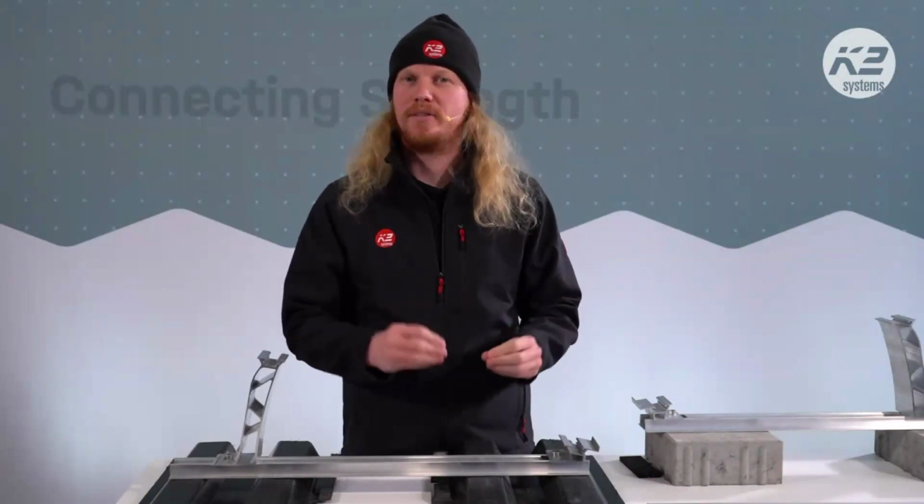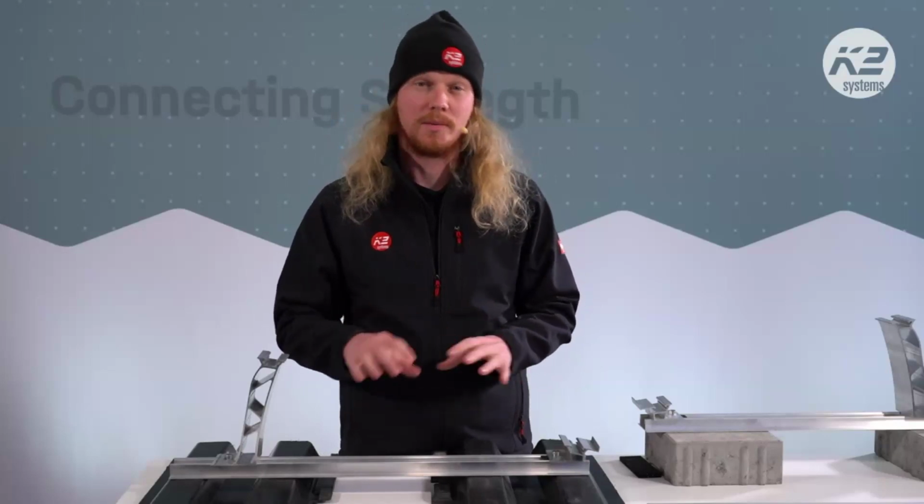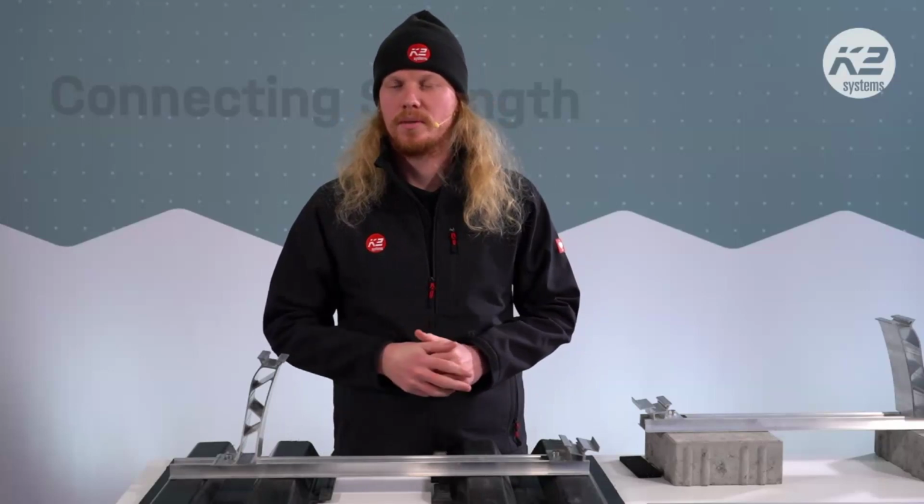It's going to be a specific topic. We're not going to focus on the basics. We're going to go into very specific details on the situation where you can put PE plates or stones underneath the substrate of your building roof, and how you can use this to your advantage to potentially avoid placing excess ballast.